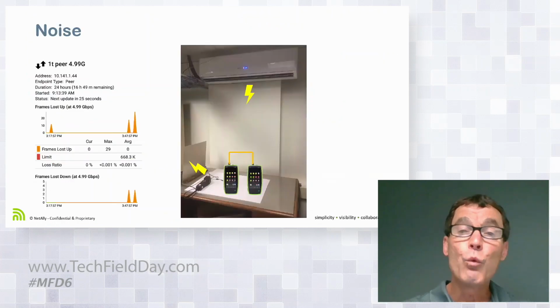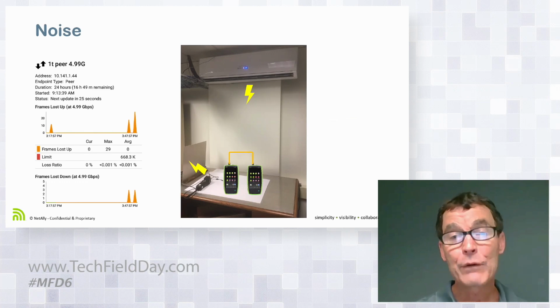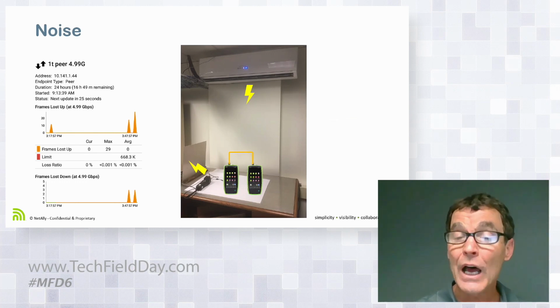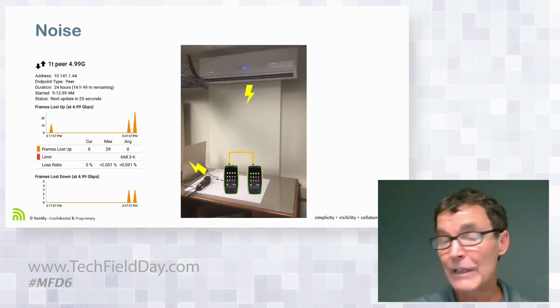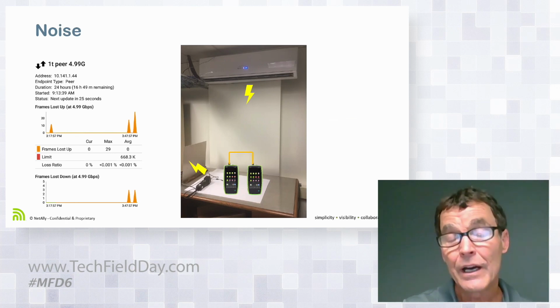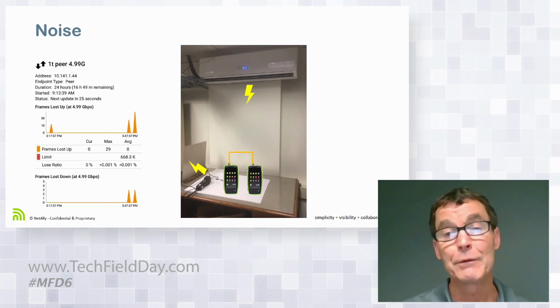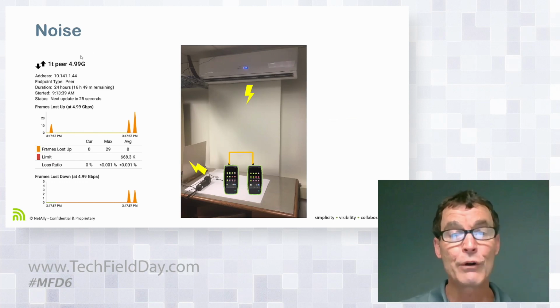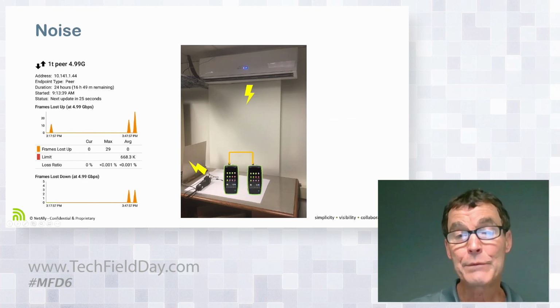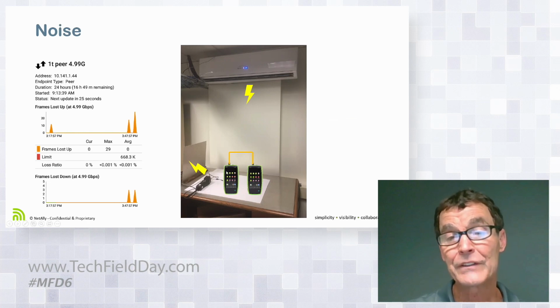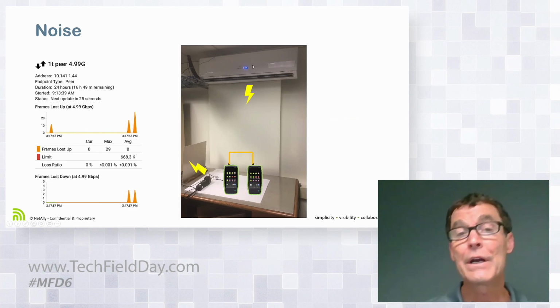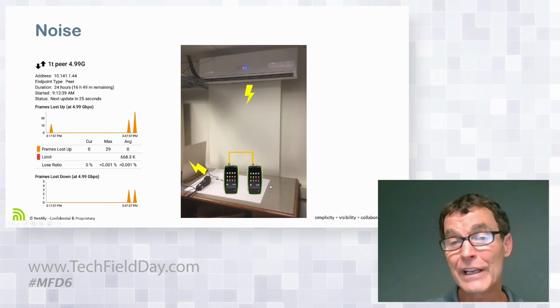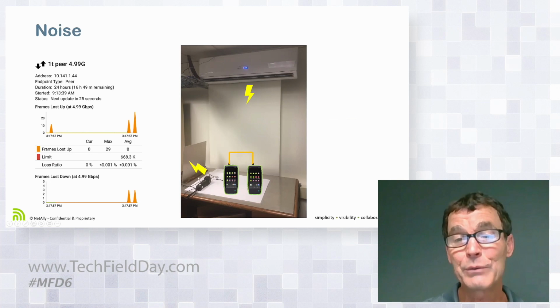So we'd actually experienced some of this, not ESD, but EMF, back when we were first bringing the Ethoscope online, understanding, is our hardware good, right? Let's run 10 gigabits through it for a week, at full line rate, and we started seeing these weird errors showing up, and I could reproduce it here with our little ESD gun, for testing, that you can shock anything and won't break it. But actually, it turned out this air conditioner above our ESD test bed was sending out a pulse whenever it turned on, and we picked that up.